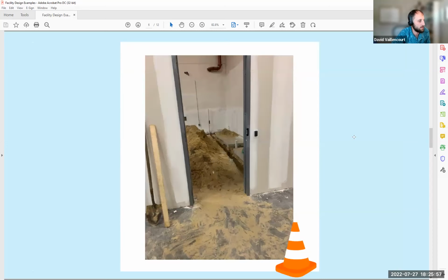I'll move on to the next photo. So this is another good example of, during the design process, making sure that you're actually thinking through what your room is intended to be used for, and realizing later, during mid-construction, that you change your mind. Oh, you want to actually produce food in here and you need a sink and you didn't actually run the plumbing beforehand. So hold on. What's the impact here? And we haven't even gotten into the interior and the cleanability of the surfaces, just putting plumbing and fixtures on the exterior of the walls. You want to have those things trenched or behind the walls. So this is an impact of really what happens with poor planning.